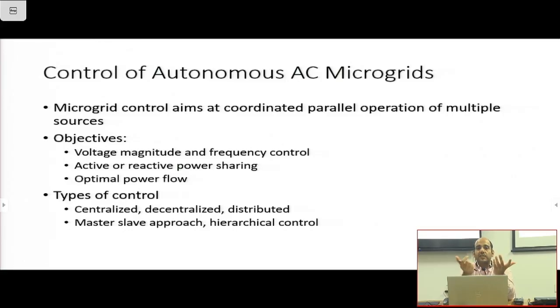Frequency control is very simple. It's an inverter, it can produce its own frequency, it doesn't need any frequency reference. So you generate your own omega frequency, 2 pi by 50, integrate it, you get theta. What is the physical significance of the theta that we are talking about? That theta is used when you finally convert dq back to ABC. The ABC quantities will have a phase, because any sinusoidal can be written as Vm sin omega t. That omega t term is the theta.